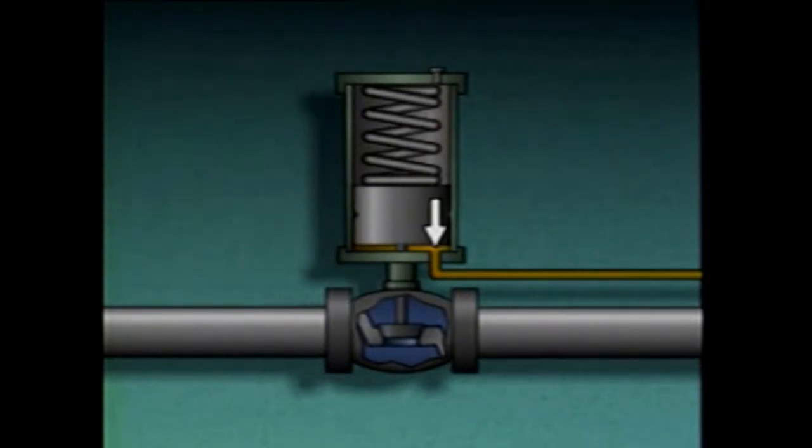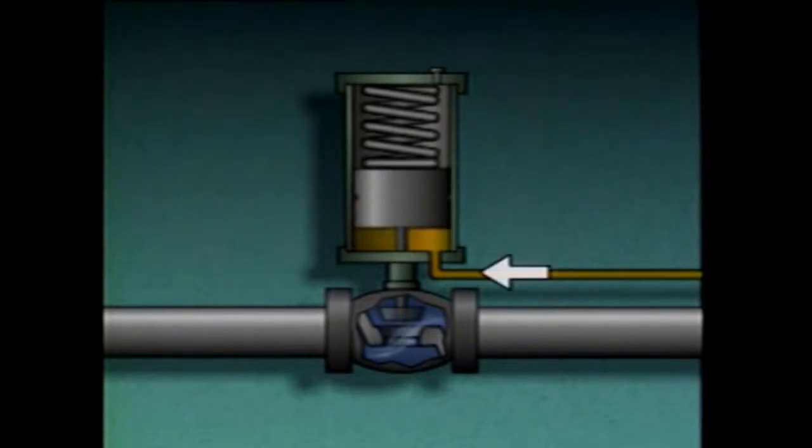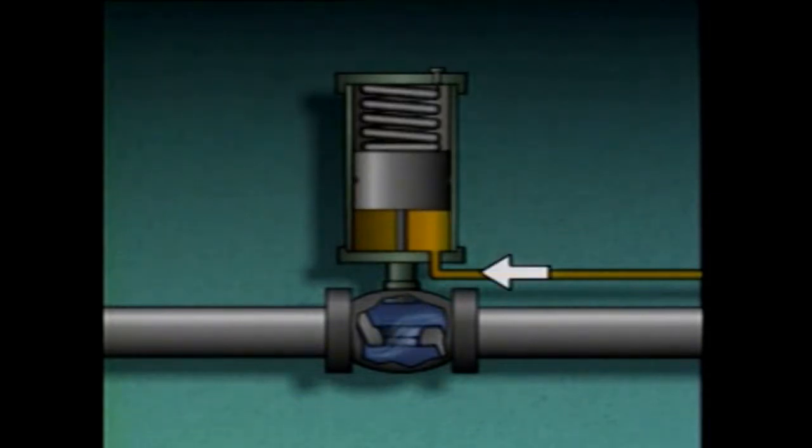The piston can be positioned anywhere in the cylinder by controlling the amount of fluid entering the cylinder or bled from the cylinder. This actuator is considered to be single-acting because fluid enters the cylinder through only one port and acts on only one side of the piston.